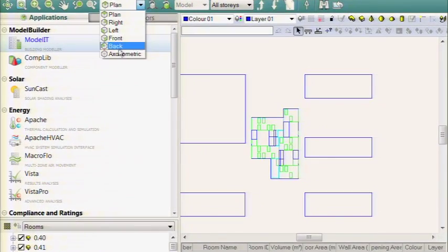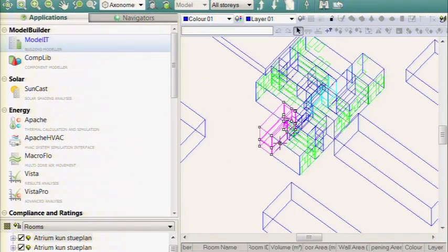Another thing that I will do a lot, as I was mentioning to someone earlier: if I have 2 floors or 3 floors that are working very well, and that third floor is repeated up 100 times in a very tall building, I might just fix those first 3, and then when I go into the VE, I'm going to copy up the rest. So with that type of effort, you're getting information from the BIM model, but you're not saying, oh, on floor 72 I have an error, and I'm going to spend 2 days trying to fix that, when I can just focus on the ones that I need to fix, and the ones that are repeated, I copy up.